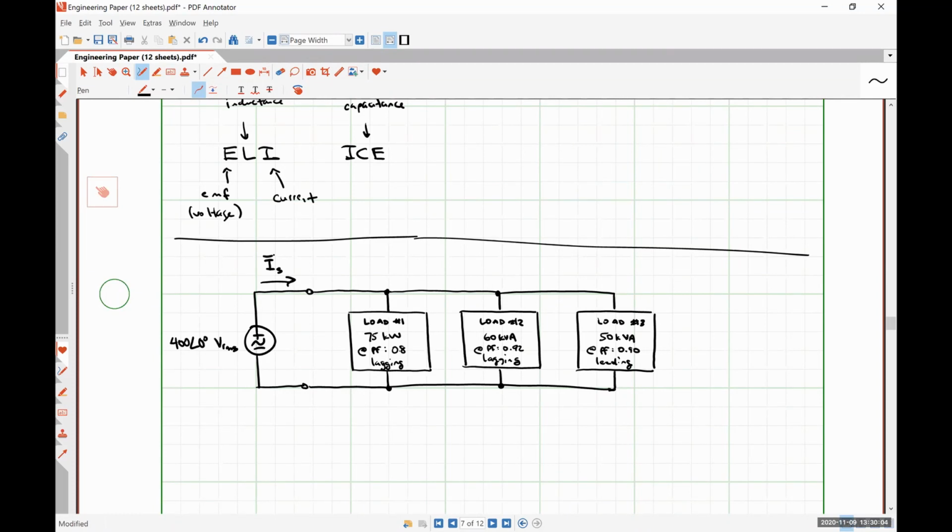So for instance, if I hooked up a microwave to an outlet here in the room, but instead of using the power cord that came with the microwave, I just effectively soldered up some of the jumper wires that we've been using in our experiments and turned the microwave on, what do you think would happen? The wires would melt. And the reason the wires would melt is because they have a limited amount of ampacity, which is a measure of a wire's current carrying capability. So if you exceed the ampacity of a wire, the insulation melts, and if you exceed it too much, the wire itself starts to melt.